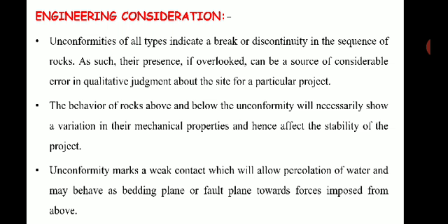Then what is the engineering consideration of such unconformity? These unconformities, of any type, indicate a break or a discontinuity in the sequence of the rocks. Their presence, if overlooked, can be a source of considerable error in the qualitative judgment about the site for a particular project.